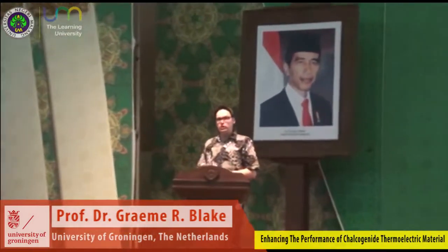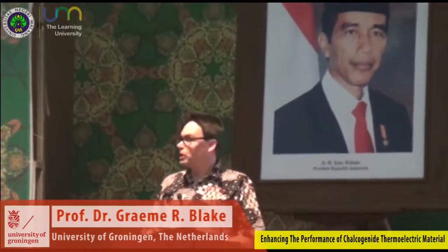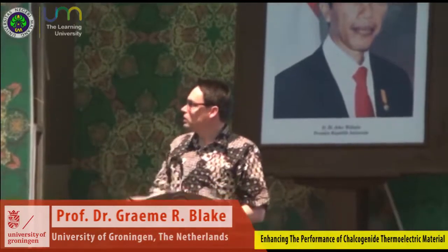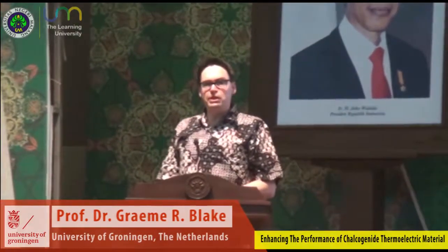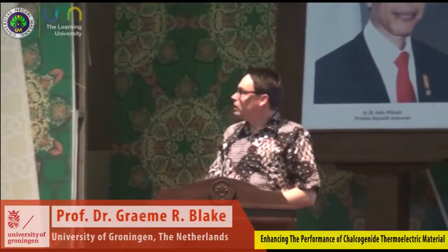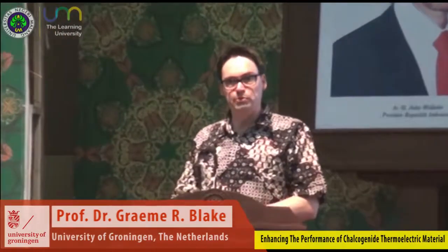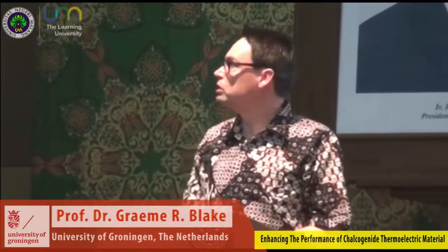Now in a thermoelectric device, the energy conversion efficiency is shown by the equation on the lower right there. So that's the quantity eta in the equation, and that is directly dependent on the thermoelectric figure of merit ZT. And we have the Carnot efficiency, which is a maximum theoretical energy conversion efficiency given by the quantity circled in green.